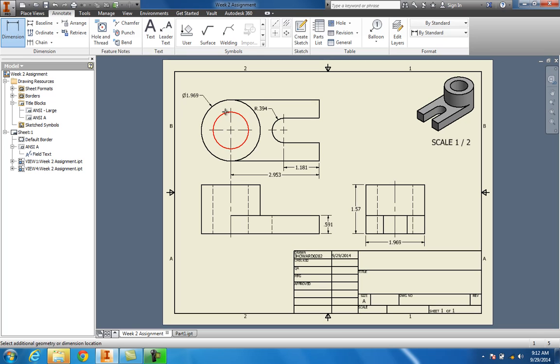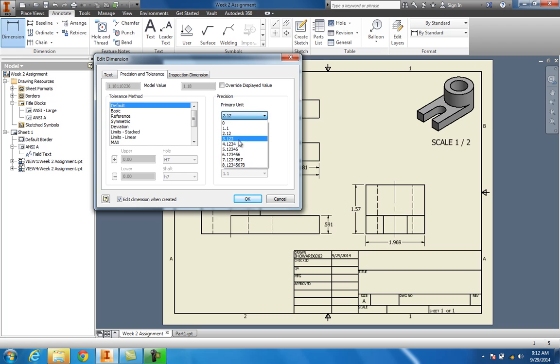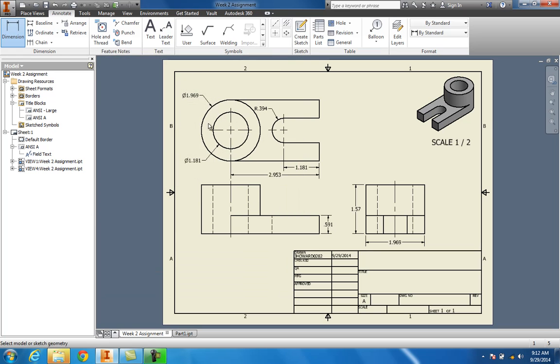And I see one more thing we'd have to have a dimension on. And also, don't forget, anything that's going to be in round stature like these are, radiuses or diameters, always try to dimension those as you see them. Don't try to come down here and tag this line or tag that line and say that's a radius of so-and-so. You always want to dimension things that you see. That's why I've got all my radiuses on this top view, because I can see those circles perfectly. Does that make sense? So it's easier to do that, and like I come down to this point, I put that dimension in, and of course this. I could have put this dimension over here, but I don't need to duplicate it.